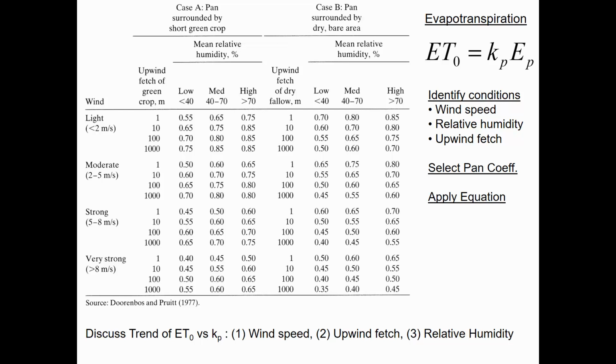But now consider, what if the pan was downwind so that upwind of it was the crop? So you have dry air encountering the crop, and the crop is emitting moisture and, in theory, because of all the moisture the crop is emitting, saturates the air so that by the time it gets to the pan, there would be relatively less evaporation from the pan.